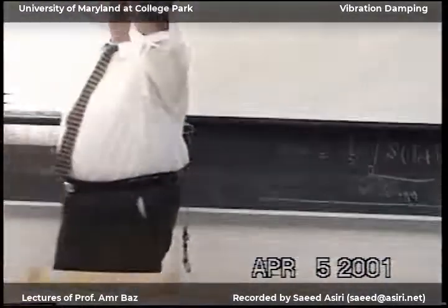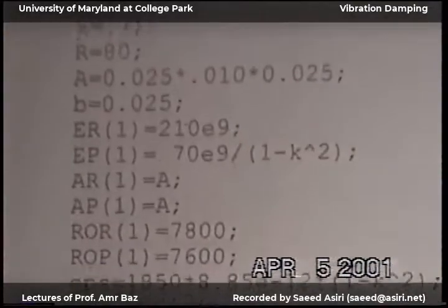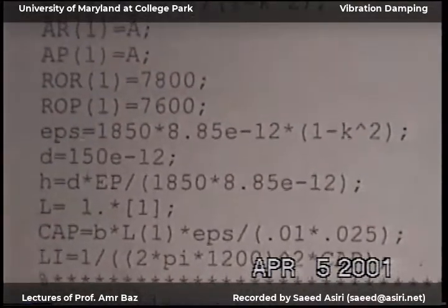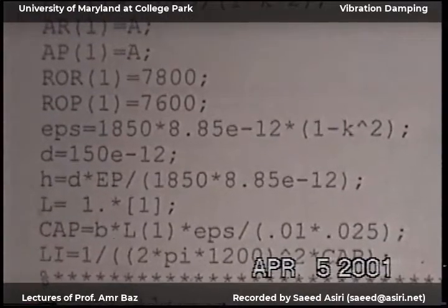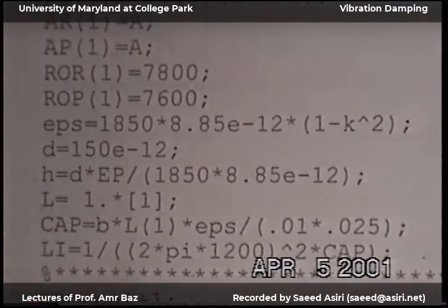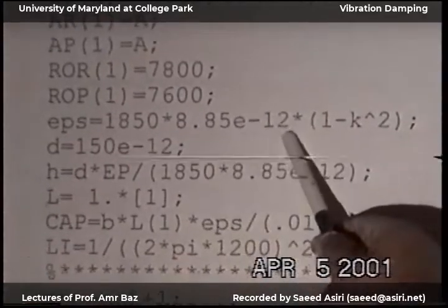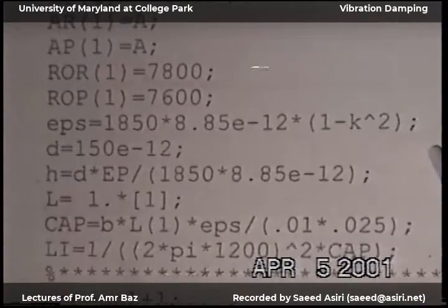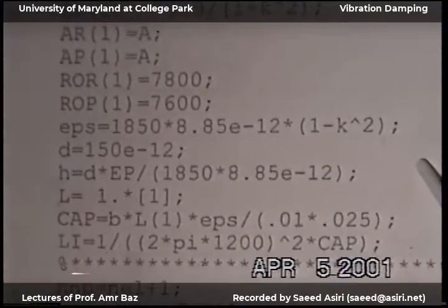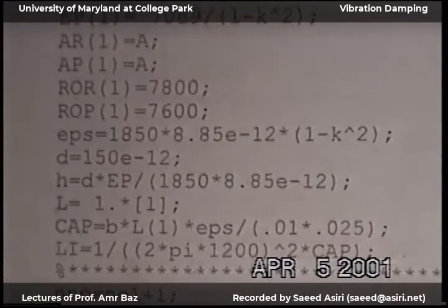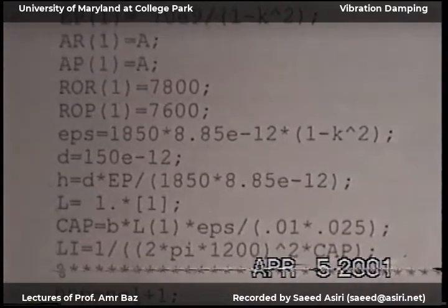This is not the regular Young's modulus, this is the Young's modulus at open circuit. And then now, the epsilon. The epsilon that we have is epsilon to the power S, or superscript S, which is at constant strain. I have epsilon at constant stress, and then I have to modify it by the electromechanical coupling factor. So you have to convert the constitutive equation correctly according to the formula that we have.